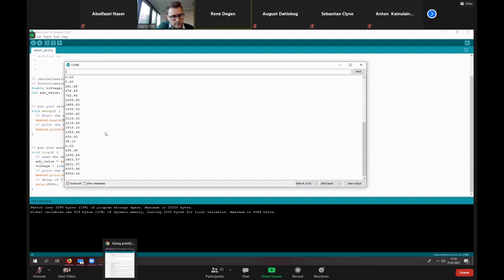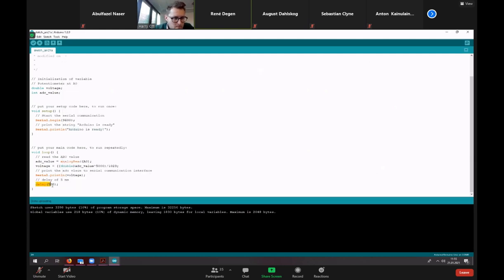But exactly, you have to add the clock time too. The delay is just how long the Arduino stays at this specific line. Additionally, the Arduino needs for each row one time the clock time. I hope you know what I mean. I think it was 16 megahertz.